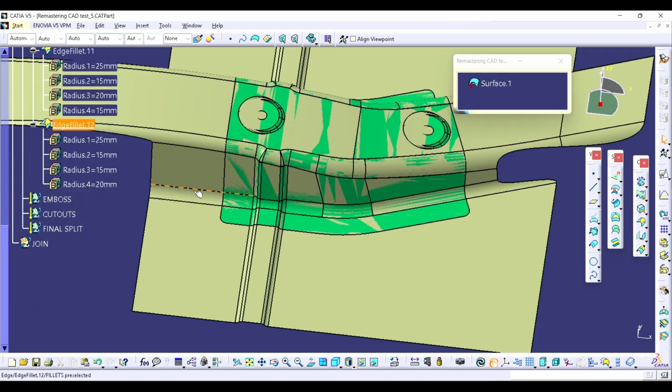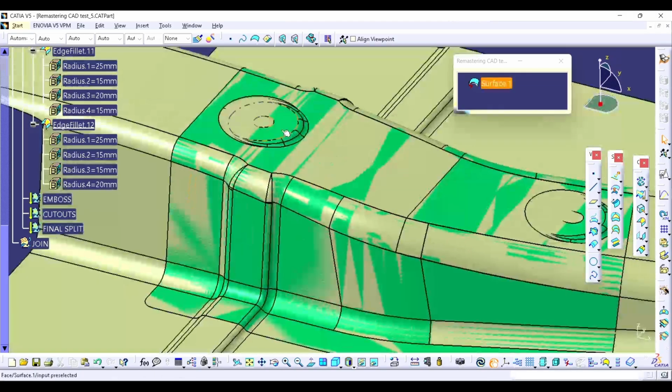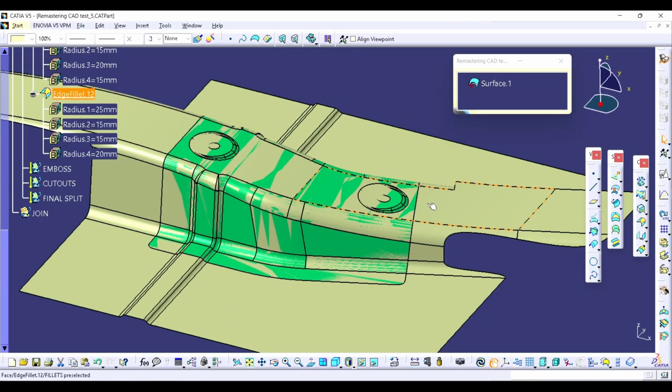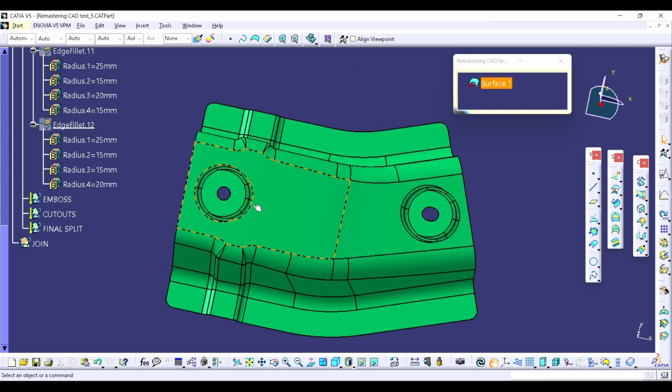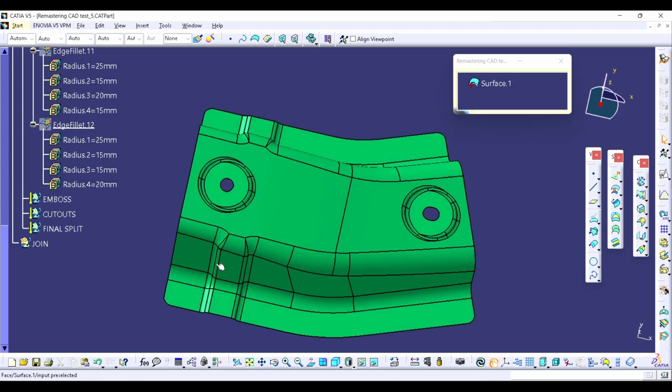Now it's time to provide the emboss. You are able to see they have created these two features. Here is one piece of technical knowledge on why they have provided this feature here: one is a hole and one is an elongated slot. This mounting purpose is for the PLP. So what is PLP? PLP means primary locating points. It helps to lock this part in the assembly sequence, so then you can provide the spot on this flange, or it helps to lock your part. PLP means primary locating points, and it should be on a flat surface.